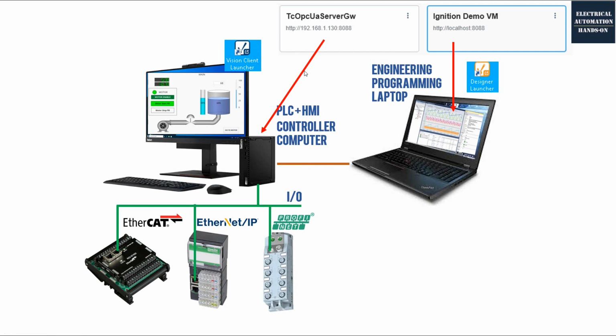So you can prepare this HMI project ahead, and when you go on site, copy and paste to the target HMI project. This is exactly the same case, and this is also the proper way I figured out, allowing you to prepare some offline program, and then go on site and copy your prepared HMI project, the screens and variables, to the target HMI server project.